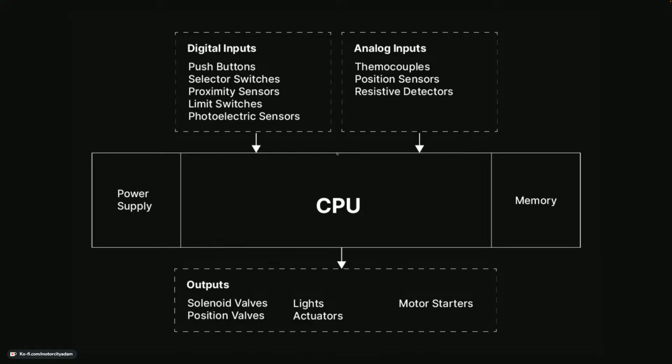So you can imagine someone walking through the door, and there's a photoelectric sensor in the door. Like a light curtain, like an invisible beam. Once you break the beam, the photoelectric sensor turns on. And then you could have some logic in your controller to say, okay, when that beam is broken, turn on a light somewhere. So you're taking an input, you're doing some logic to it, and then you're affecting the real world. You're doing some action that impacts the real world.